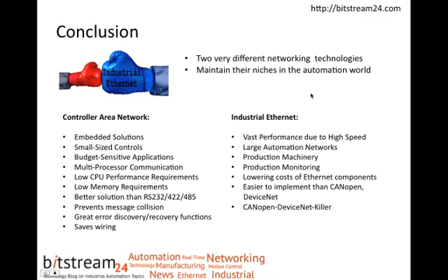Industrial Ethernet's vast performance unfolds specifically in the larger networks for automation and control of production machinery, including production monitoring. The performance and decreasing hardware costs make it a fierce competitor, if not a killer, of other established networking protocols, including, but not limited to, CAN, CANopen, and DeviceNet. And of course, it requires significantly larger hardware resources than CAN, but the result is well worth the expense. Industrial Ethernet will reduce development and design costs compared to CAN, CANopen, and DeviceNet because it does not require any time-consuming performance tweaks.